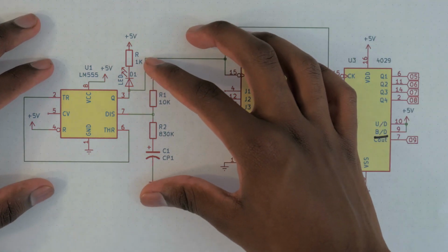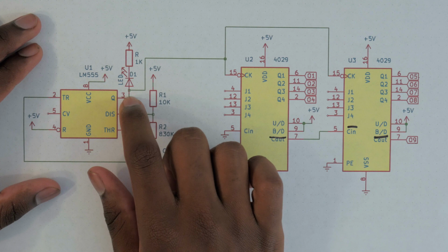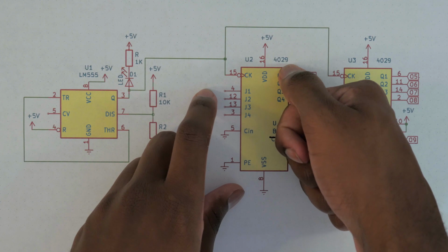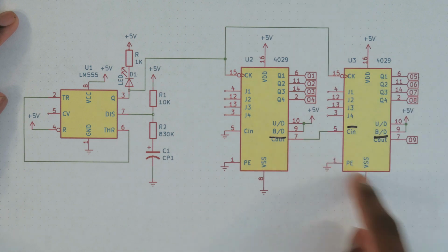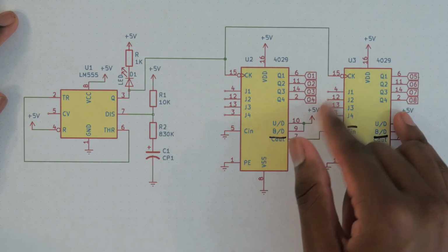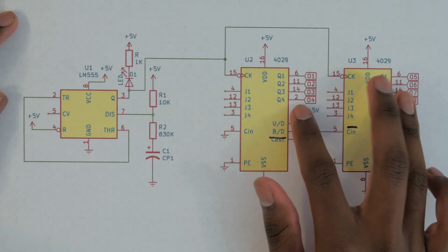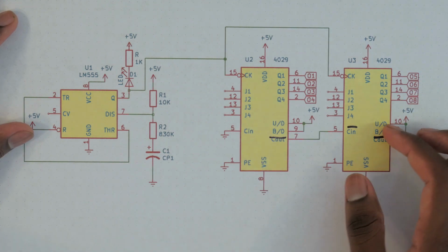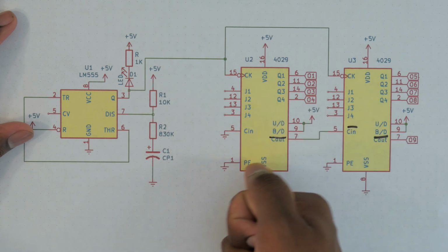This portion is just a smaller version of the circuit you just saw, which is the 555 timer. We have the clock signal of the 555 timer going to the clock pin of the 4029 counter, and on this first chip, we're cascading 2 of these chips together because each of them is only a 4-bit counter, and we're using 2 of them to get an 8-bit counter. These outputs are not going directly into the EEPROM, and we'll explain that in a little bit, but right now this is just the counting portion. The carry in for the first chip is tied to ground because we're not carrying anything in.